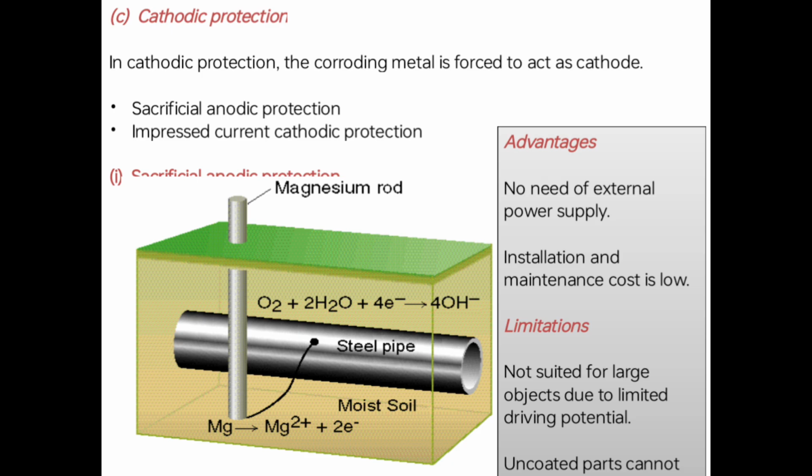Advantages: no need for an external power supply, and installation and maintenance cost is very low. Limitations: not suited for large objects due to the limited driving potential, and uncoated parts cannot be protected.